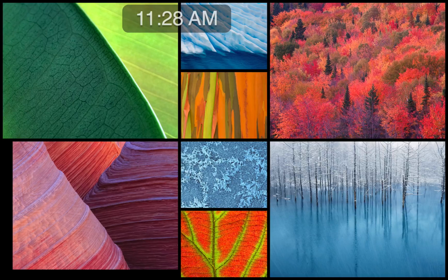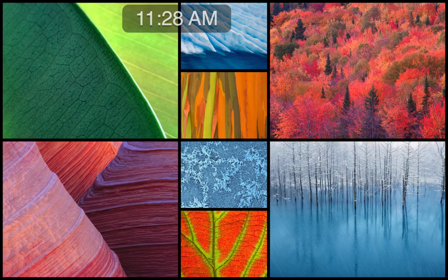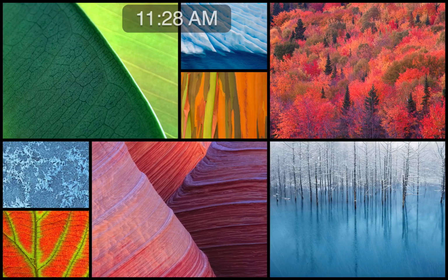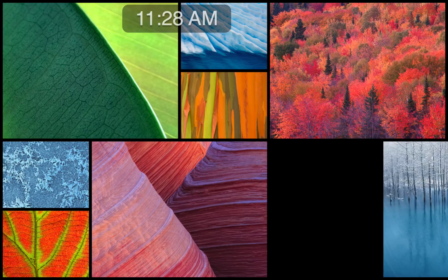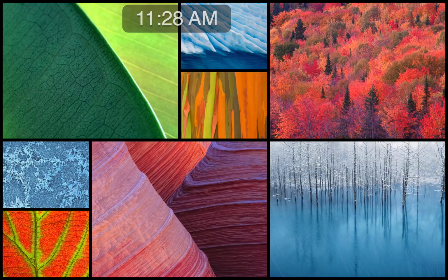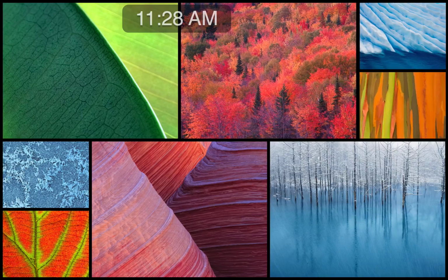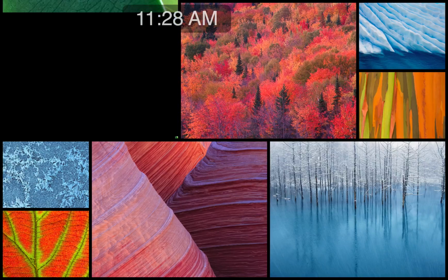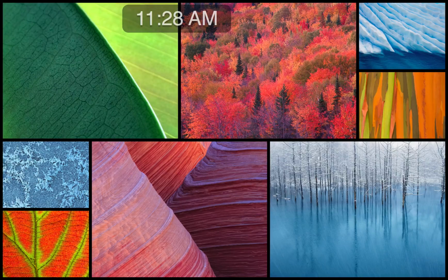And then I'm gonna copy these. I'm gonna copy all this stuff, except for the wall. So how do I get rid of the wall? I just selected everything there. How do I get rid of the wall? Your best friend, filter. Get rid of the walls, okay? Then I can just copy this from, and I gotta zoom way in here because I want to make sure I'm getting this. And then I want to go to this reference plane.